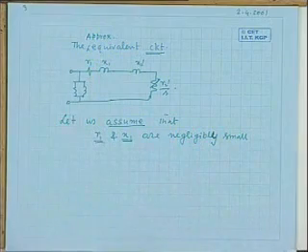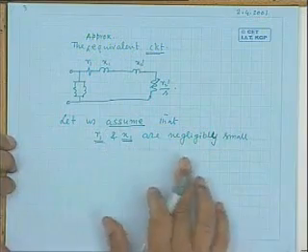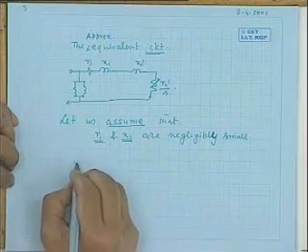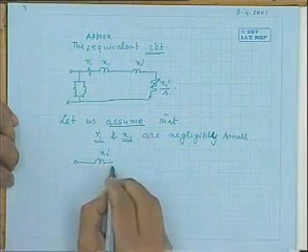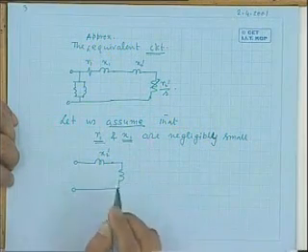To find out how the basic properties of the machine can be found out rather easily if you neglect R1, X1, that we will do first. So if you do like this, then this equivalent circuit will be very simple. This is as if all the power you give becomes your air gap power and goes to the rotor.